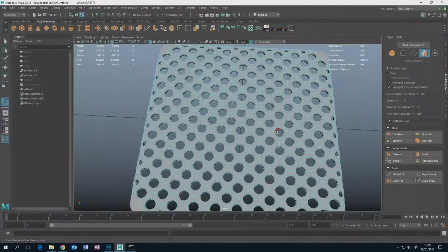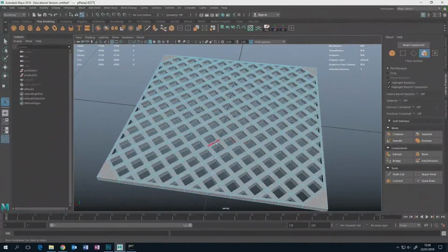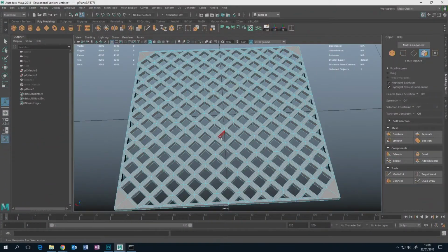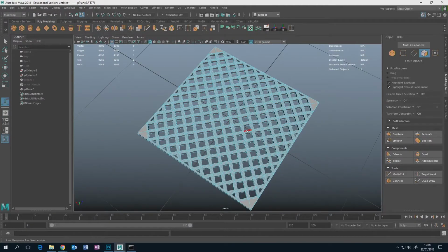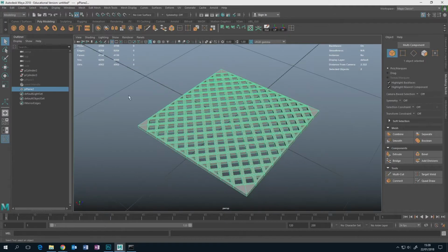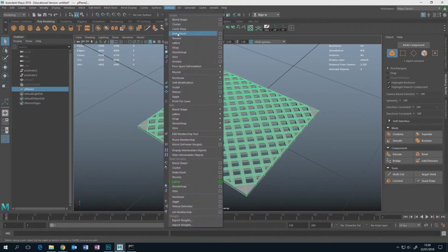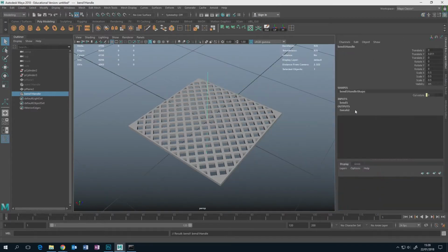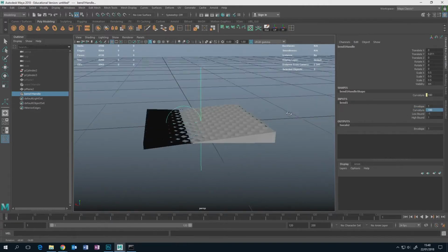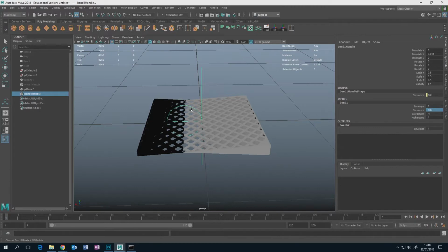That's quite nice. Now how could I use this in conjunction with the bend modifier to create something even more ambitious of a shape? So if I apply the bend modifier to it, the nonlinear bend, curvature. So I'm going to put this to 180. Initially it's going to kind of distort because I've got to reorientate this bend handle.